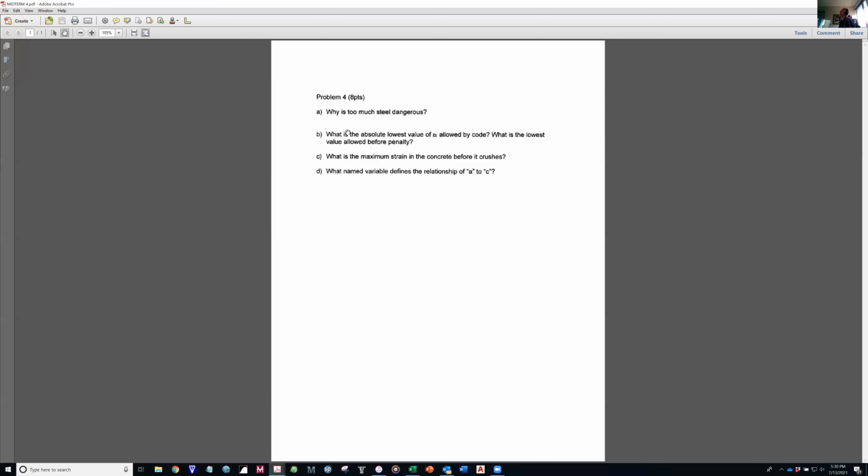Any questions? Wait, can you repeat letter B? Letter B, yeah. 0.004, 0.005. 0.004 is the lowest allowed by code. Oh, I thought it was 0.003. That's the answer to part C. 0.003 is the maximum strain in the concrete, but epsilon sub t is the strain in the steel. So the lowest allowed by code in the steel is 0.004.